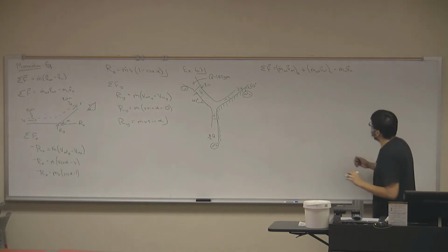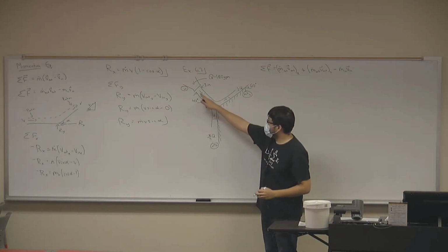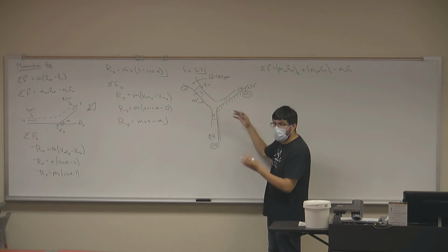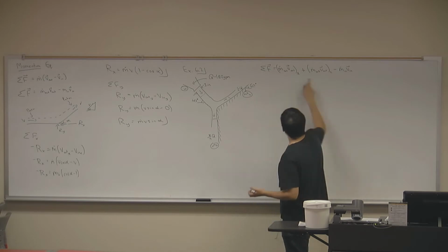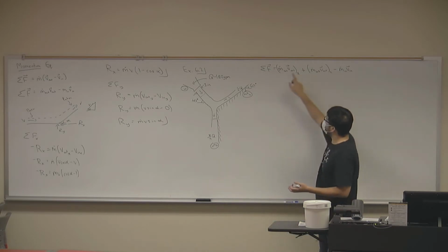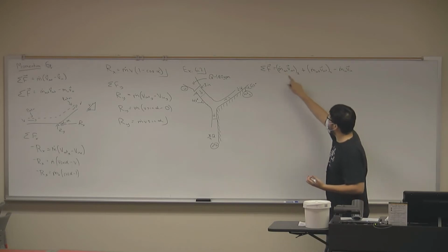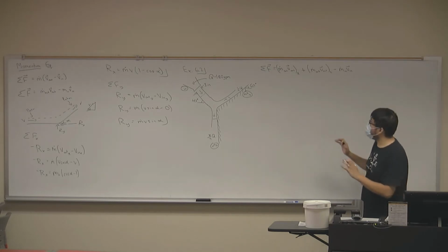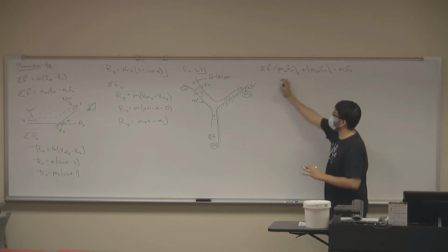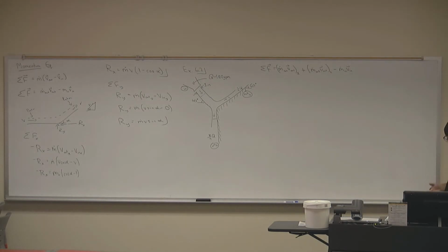velocity in. Now, why am I not factoring out the mass flux? Because notice that whatever comes in will go out, we know that. However, because it's being distributed, this mass flux in is not equal to this mass flux out, right? And it's not equal to this mass flux out. Rather, it is the sum of these two that will equal this mass flux in. So we can't factor it out just yet. We can't just say, okay, factor out mass flux and you've got your velocities. We need to consider what is the distribution of flow in the system.